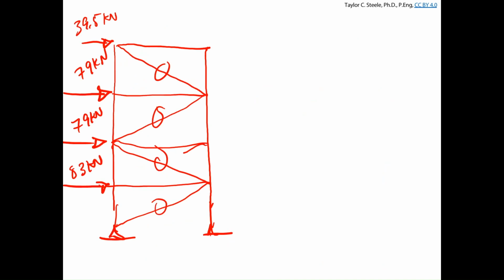And you should be able to differentiate between statically determinate and indeterminate bracing, as well as tension only or tension compression bracing. Before you wrap up, is this tension compression bracing or is this tension only bracing, do you think? Who said both? Can it be both tension only and tension compression? I've kind of made it a little bit weird here because there's one brace, but if wind pushes the building this way, we've already known this is going to be in tension, but if the wind's coming the other way, it's going to be in compression. It has to be designed for a tension force and a compression force. We cannot make it tension only, because if the wind pushed the other way,